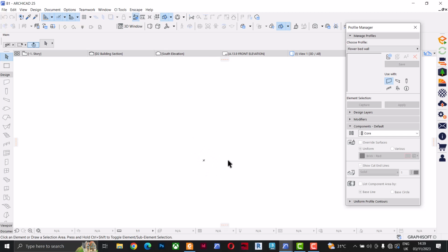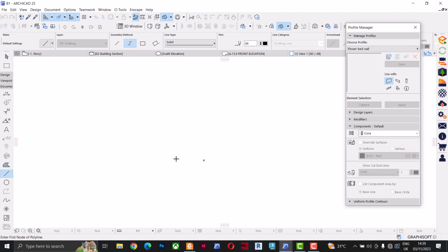This point here is going to be your reference, where your reference line will be. So keep that in mind. Whatever you're drawing, make sure where you want your reference line to be is where this point starts from. So we're going to use our document option. We're going to use line now to draw out the section of our wall. That wall was 750. So we're going to make the line 750 by say 150 thickness, 6 inches block, right?